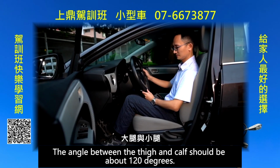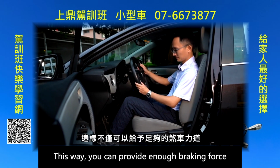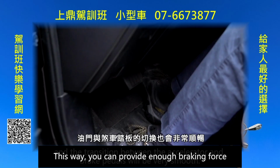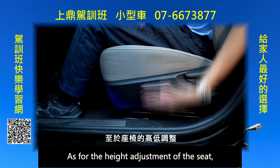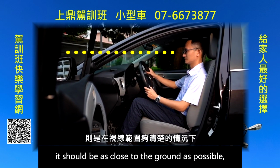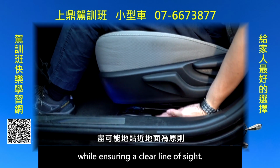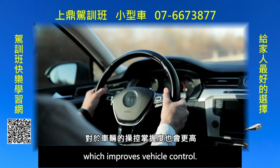The angle between the thigh and calf should be about 120 degrees. This way, you can provide enough braking force, and the transition between the accelerator and brake pedals will be very smooth. As for the height adjustment of the seat, it should be as close to the ground as possible, while ensuring a clear line of sight. This way, the center of gravity is lower, which improves vehicle control.